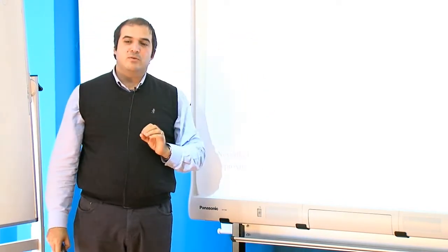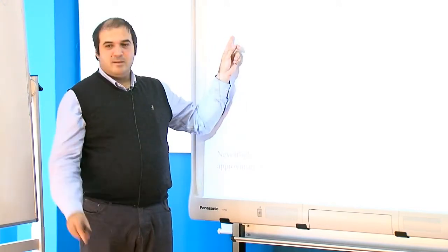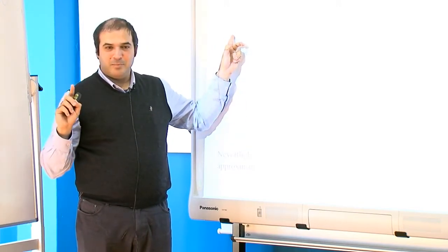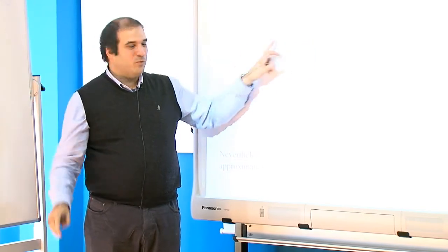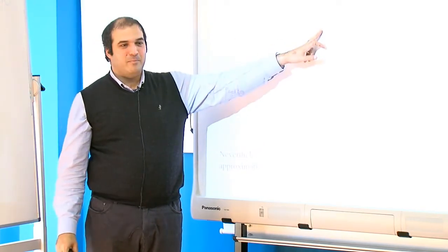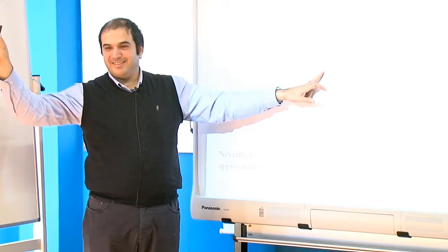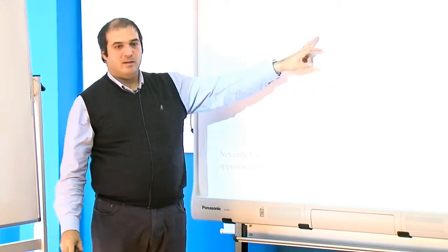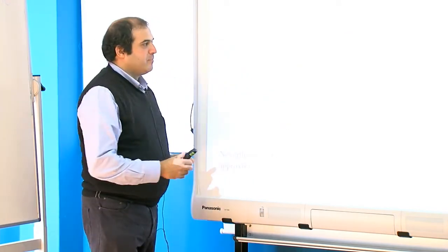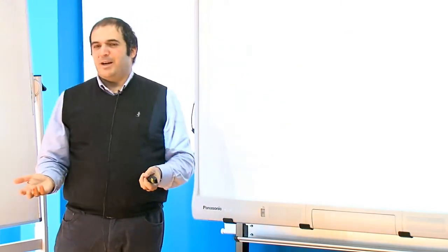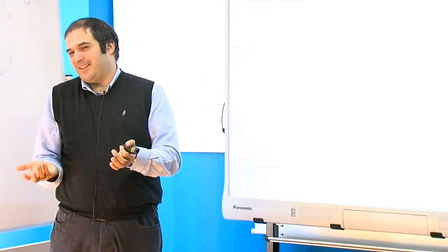It's very important to consider here one thing. This doesn't exist. What that means, the amplifier never goes there. Okay? If you try to operate your device at the IP3 input power, it will burn. Why? Because this is an extrapolation. Okay? Which means that you can say, okay, so why do I need something that doesn't exist?